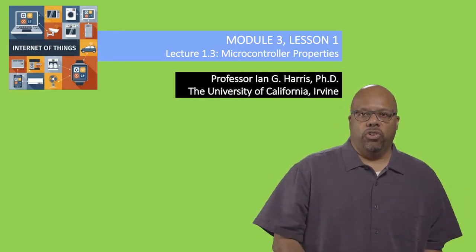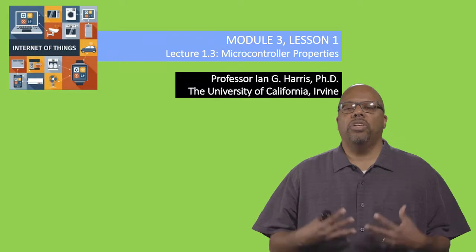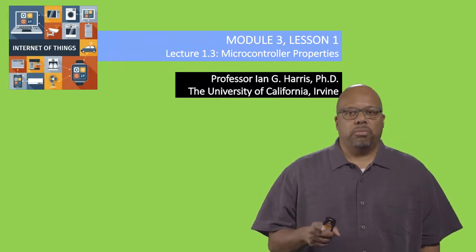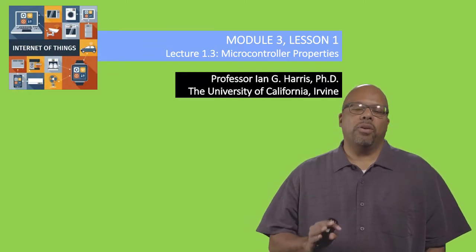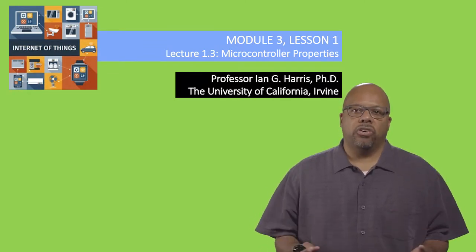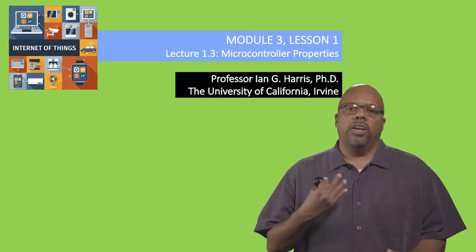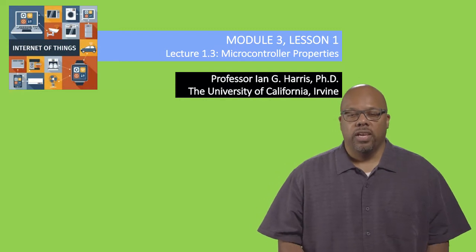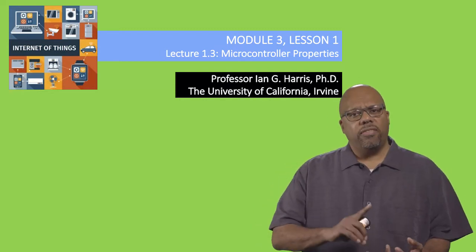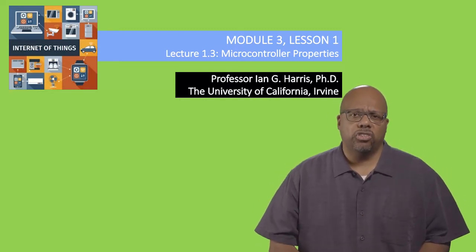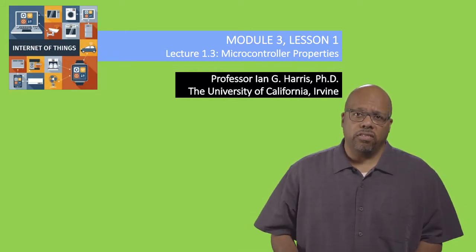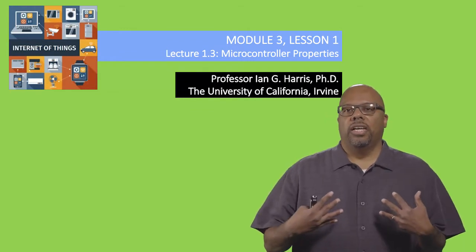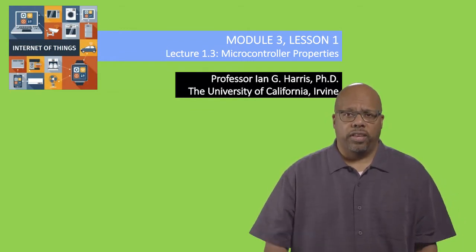Because you don't need 4 cores. You don't need that kind of clock rate. You don't need everything that it has. IoT-based systems, those things are cheap, okay? You want to be cheap. You do not want to buy some big, powerful microcontroller that you don't need. You're always saving money, trying to say, look, what is the cheapest thing that just barely does what I need to do? So what you need is to have in mind a set of characteristics that your microcontroller needs, sort of the bare minimum for your system, and then you look through the data sheets for the microcontrollers to figure out which one has that, just barely, which is the cheapest one that has that.